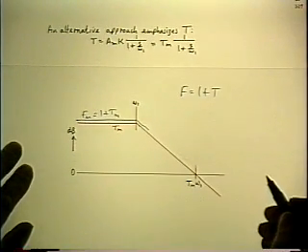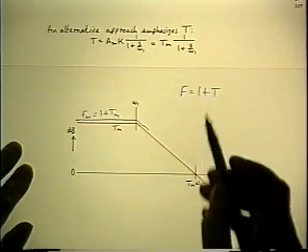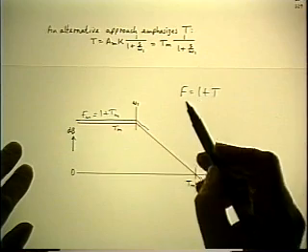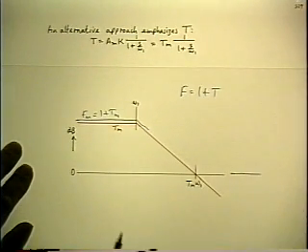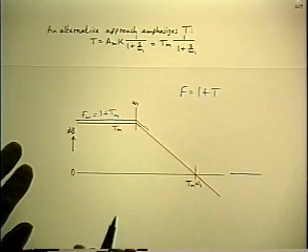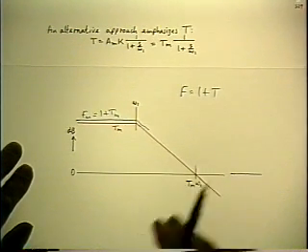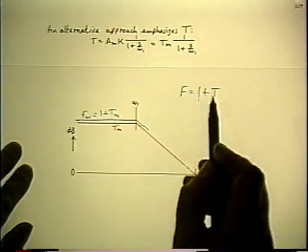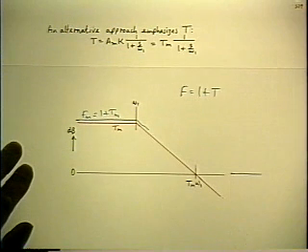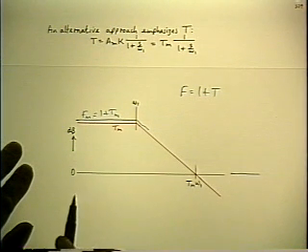Now I'll jump to infinite frequency. T has gone away. The only function left is 1, F is 1, which is 0 dB. The only part that I don't know is how to join these two together. Again, this is not an exact geometric construction because you don't add two functions by adding the dB. It's whichever one is larger dominates.